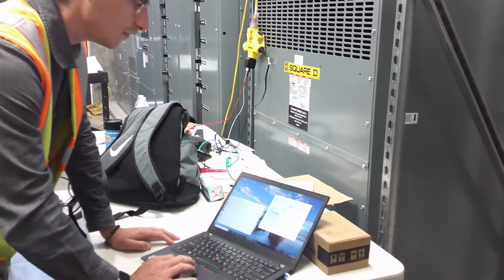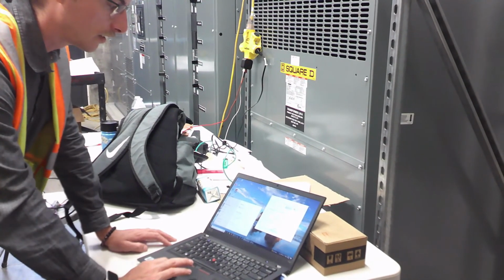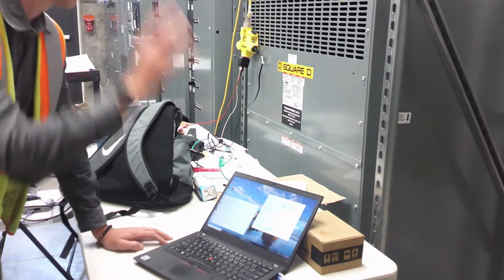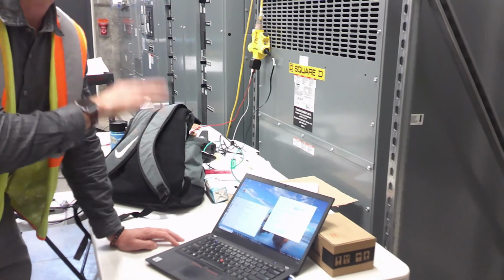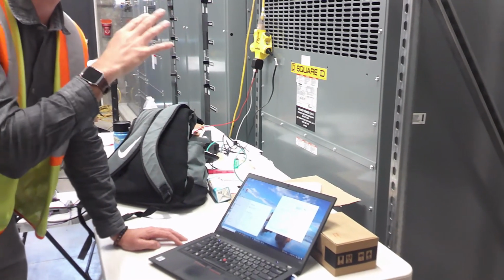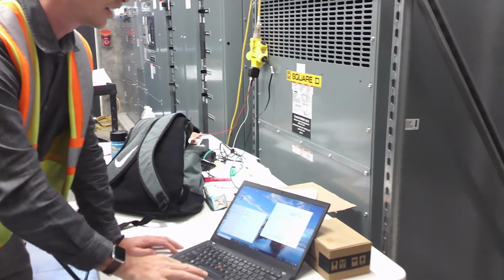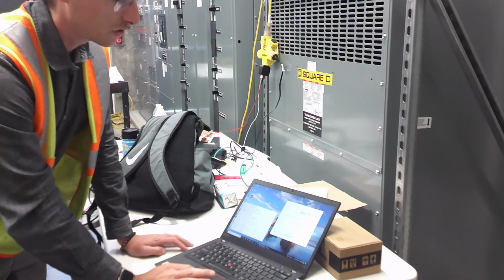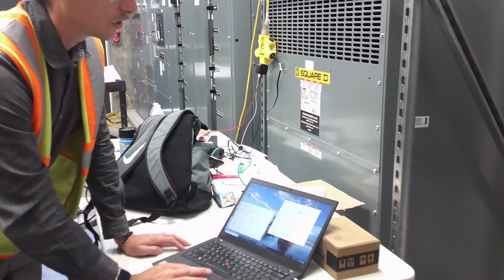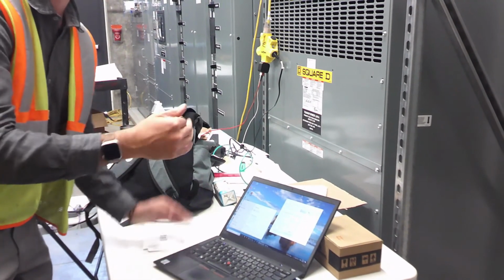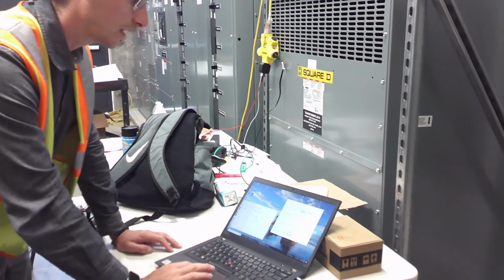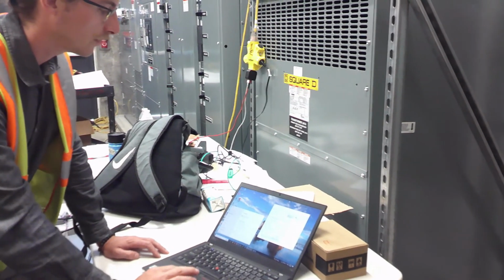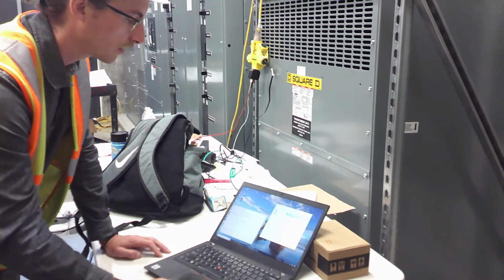Same as cameras. So we'll double click that, and then we're going to use a manual IP address. The IP address of the controller currently, which could change down the road if it gets set up for the network, but the default is 192.168.1.1. I have my computer set to 192.168.1.2. You don't want them to be the same, or else they're going to collide. And then the subnet mask default will do, 255.255.255.0. Hit OK, hit OK.